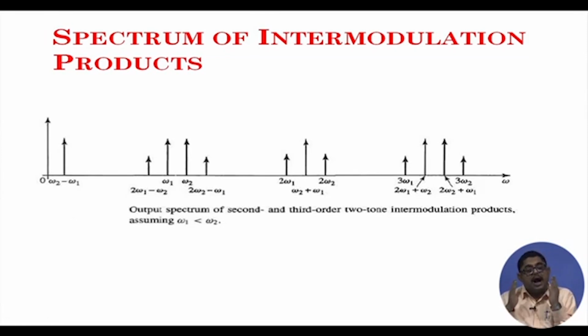When I have large signal level, I have nonlinearity present. In small signal also nonlinearity is present, but due to small signal level its value is much less compared to my desired signal. So, even if it is present, it does not disturb, but at high values they are comparable with my desired frequencies, and by filtering I cannot remove the third order intermodulation.